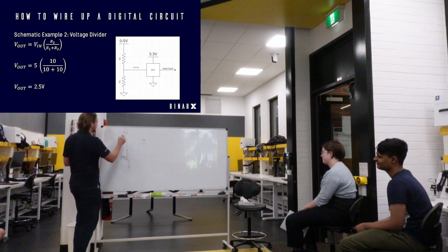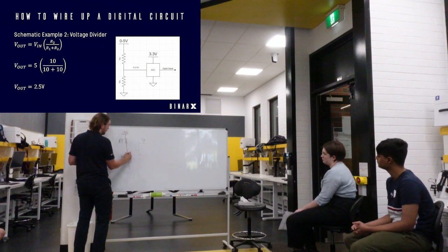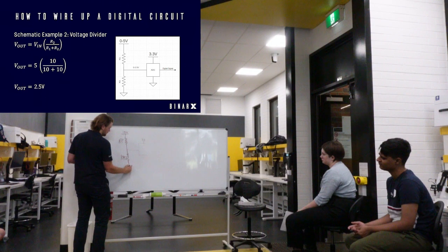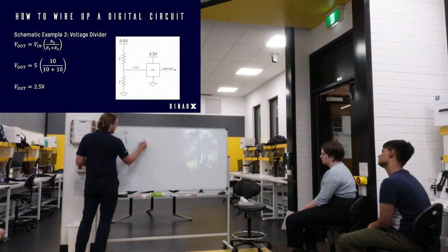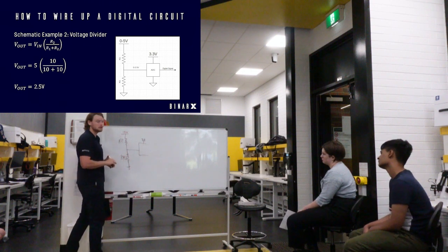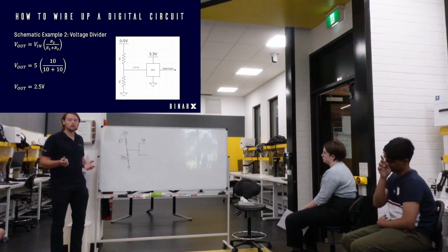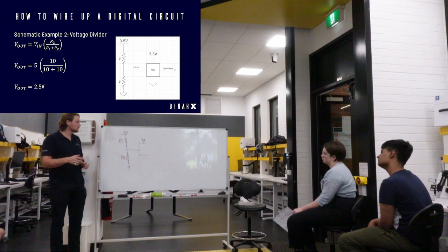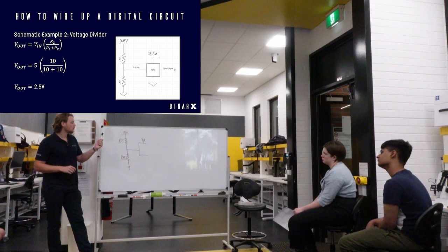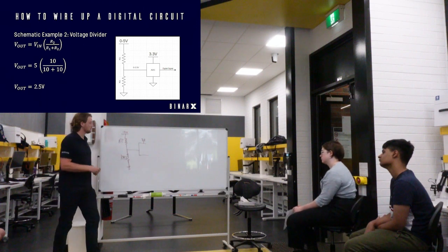All right. Psychedelic. And you use these voltage dividers quite a lot on the satellite, don't you? All the time, yeah. So our solar panels read voltage depending on their illumination from 4.8 volts to 0 volts. And so if we want to check if the solar panels are working or if the solar panels are in the sun, which is really useful for directional information of the CubeSat, we have to use a voltage divider to read our voltage into our microcontroller.